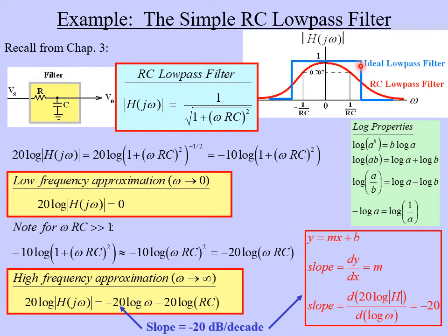So notice that at low frequencies, near 0 radians per second, the filter produces an output of 1. And we can see that here in the mathematical form too. If you set omega equal to 0, you basically have 1 over 1, which is 1. So this filter basically doesn't do anything to low frequency signals that are coming in over here. They go right through this filter without any change. That's because this capacitor basically is invisible to low frequencies. It's almost like it's not there, so the output and the input voltages are just connected directly together.